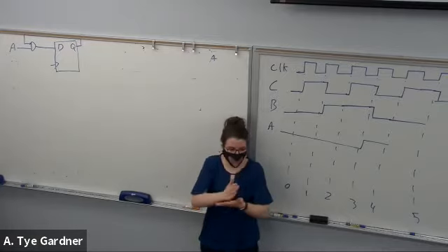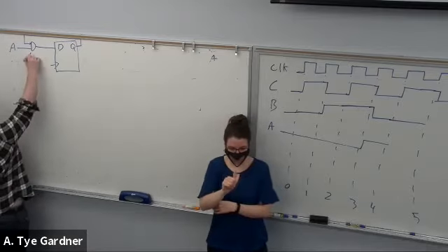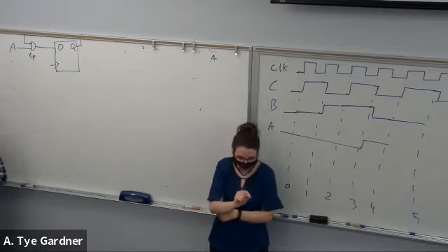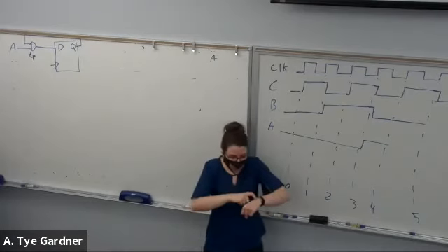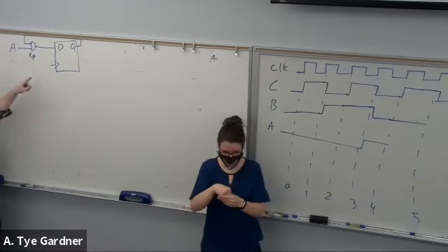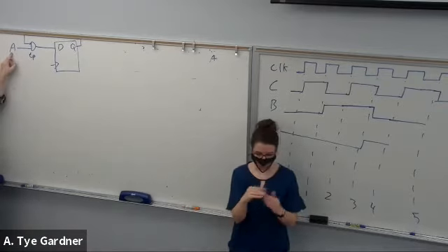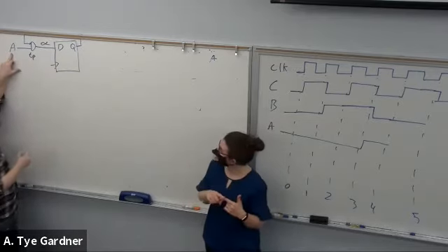So a couple different types of delays and other timing characteristics that we're interested in are as follows. First off, you have what's called a propagation delay, or something that I'll call lowercase t p, t propagation. That is how long it takes for the gate to react to a changing input. So if I change, let's say Q was 1 and A is 0, then this node, I'll call it alpha for now.